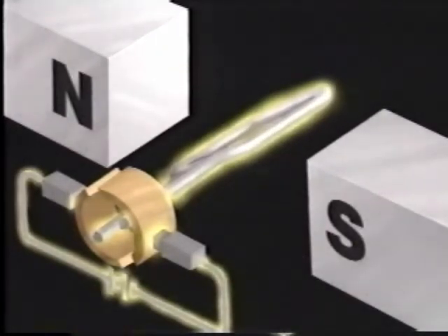Because the armature is U-shaped, its flux lines change direction relative to the magnetic field flux lines on opposite sides of the armature. To see this more clearly, let's look at a graphic representation of a side view of the armature. The two circles represent the left and right sides of the armature. On the left, current is flowing toward you, represented by a dot in the circle. On the right, current is flowing away from you, represented by a plus inside the circle. You can think of it as the tail of an arrow as it moves away from you.